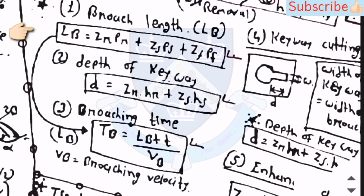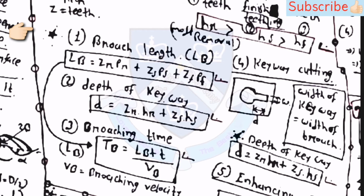Here you can see that HR is greater than HS greater than HF. It means the height for roughing teeth is greater than the height for semi-finishing teeth, which is greater than that of the finishing teeth. Then the broach length LB is equal to ZR into PR plus ZS into PS plus ZF into PF. Then depth of keyway D is equal to ZR into HR plus ZS into HS. And the broaching time TB is equal to LB plus T upon VB.